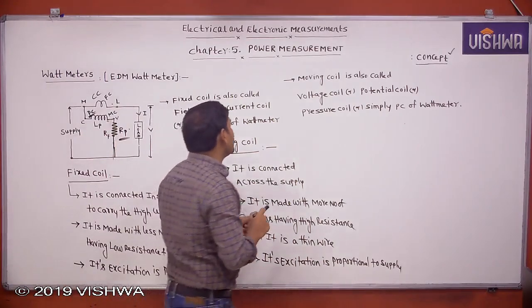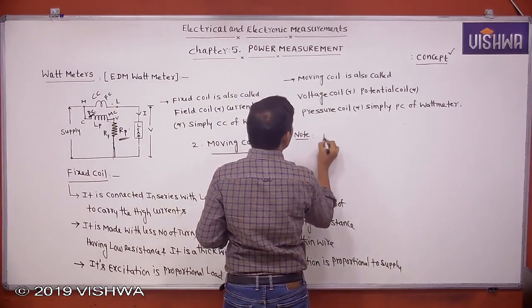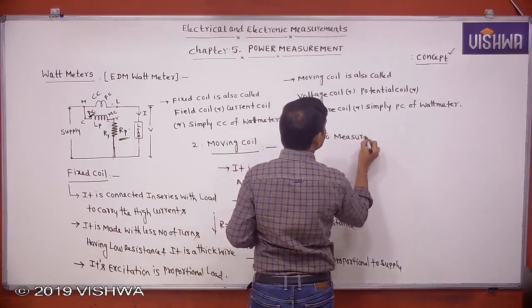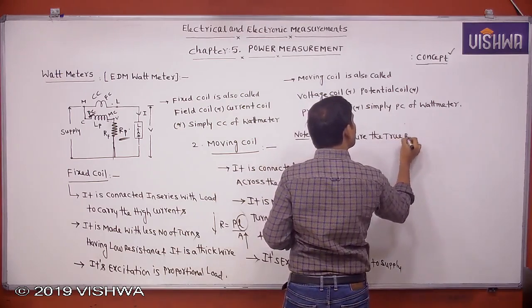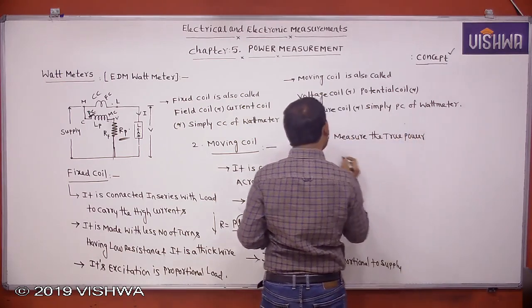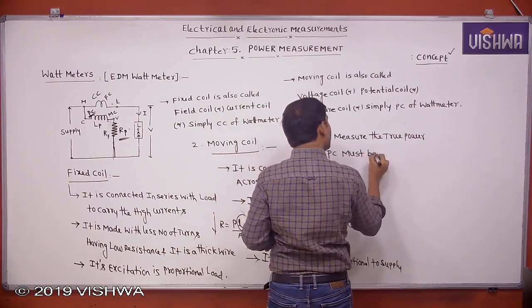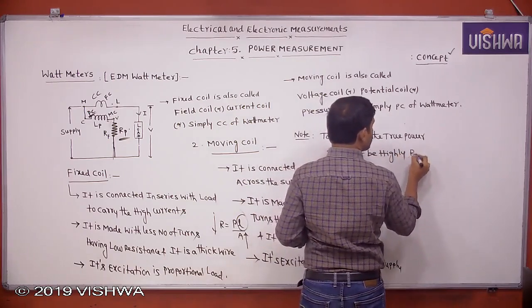This is a very important statement. Write this as a note, already framed in competitive exams. To measure the true power, pressure coil must be highly resistive.